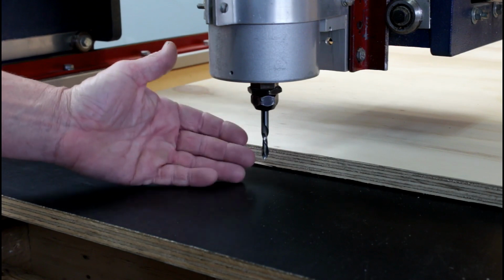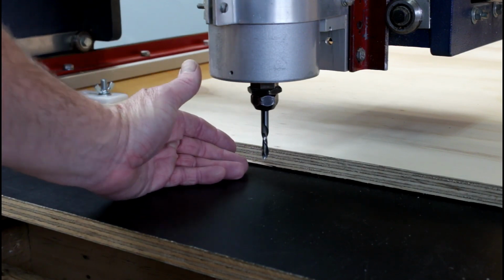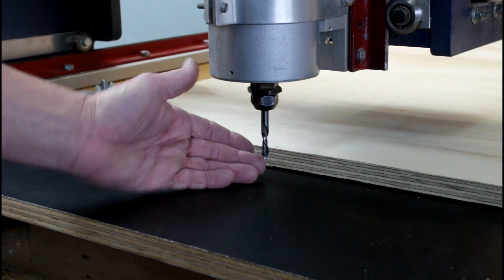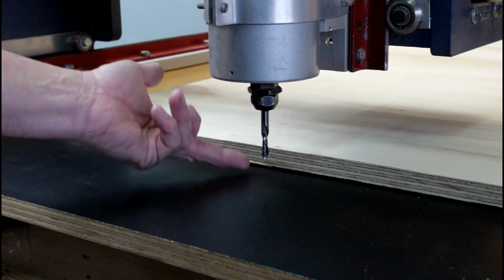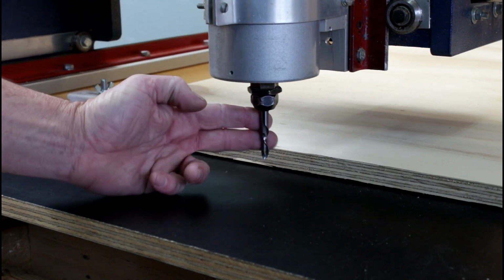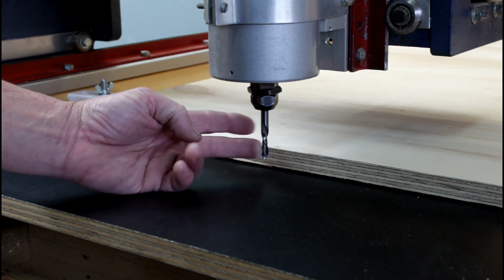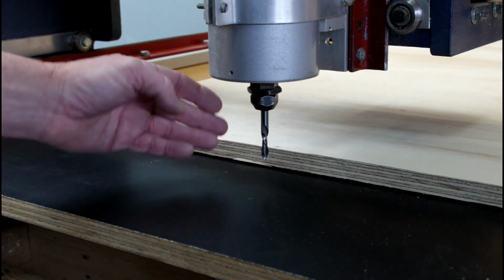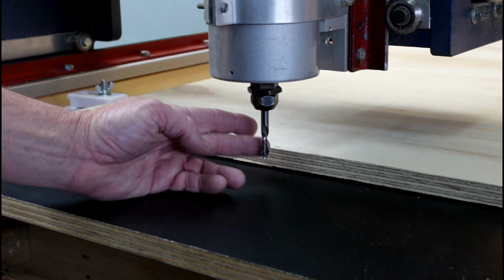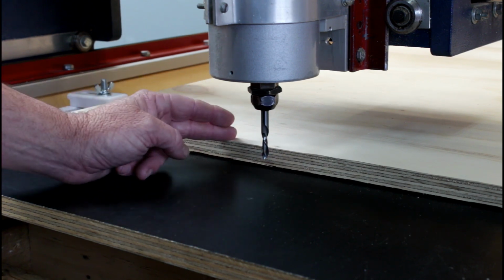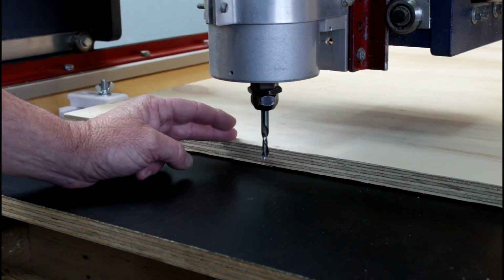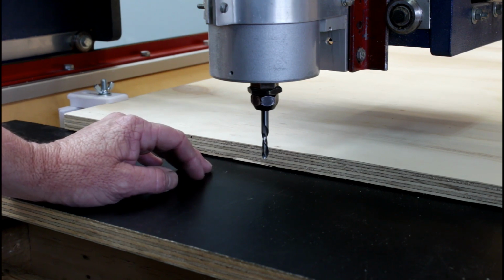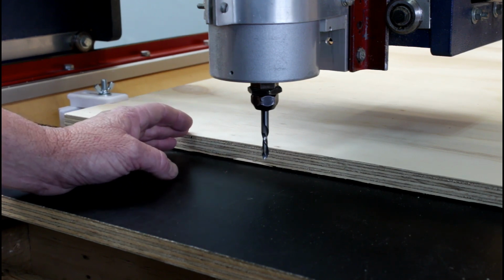The cutter is now back to the original setting I had before I started all this. It's now set to the surface of my spoilboard as I usually use it. When I cut through this material, it will not scar up my spoilboard, but will cut through the material. So we'll see at the end of this cut how this method works and what sort of damage I've done to the spoilboard.